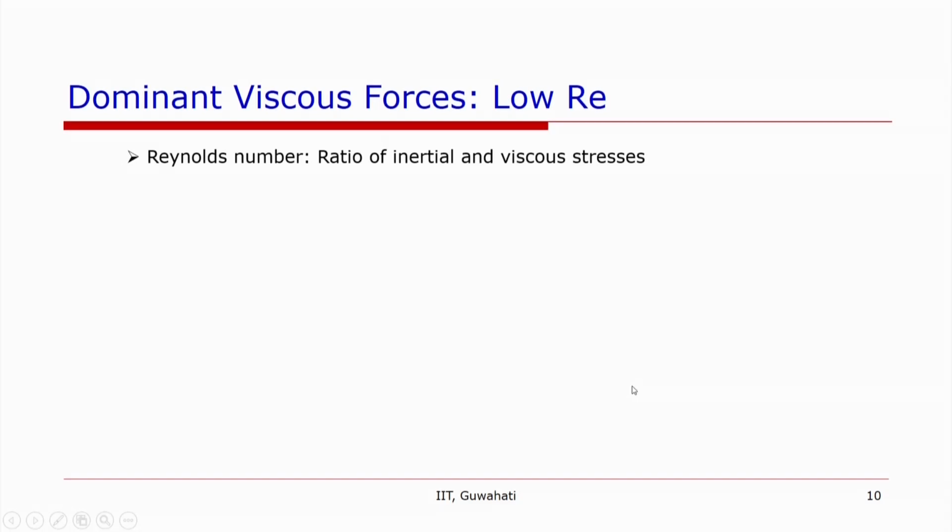Now, coming to the third effect, which is another surface effect: in microchannels the viscous forces are dominant. They can be represented by a Reynolds number, which is the ratio of inertial forces and viscous forces, or in terms of the stresses. Reynolds number is generally defined as rho d u over mu, where u is the velocity of the fluid.